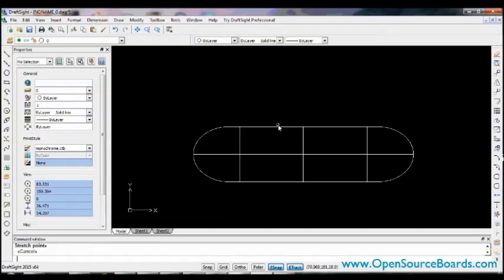The next step is going to be to place the bolt holes. This is really helpful if you're going to be laser cutting your veneers beforehand. I only do this for one veneer, and I do it on the bottom veneer. When I glue up all my boards, you can't align everything perfectly all the time. So I'll put the holes in the bottom veneer so that when I go to drill my holes, I already have the holes drilled perfectly where they need to be, and I know my alignment's going to be perfect.